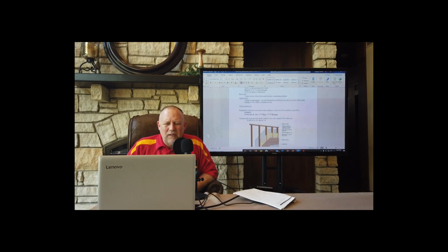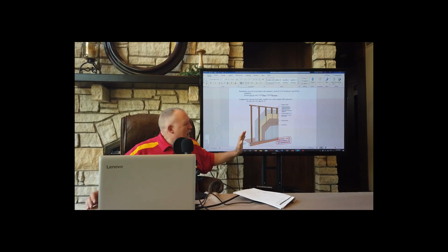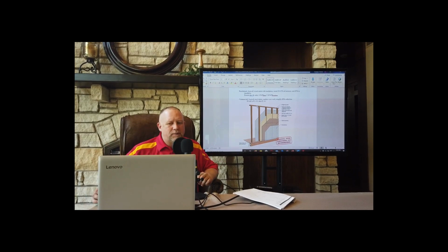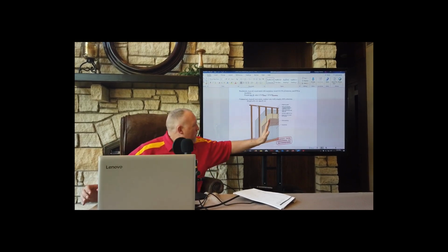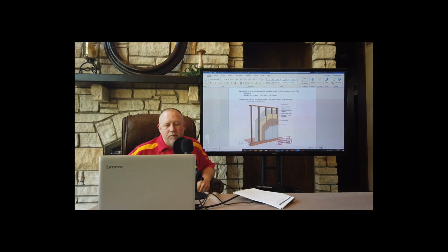Notice this. Go to page 14. So what a wood wall does is basically it's like two different walls, where one path through here goes through the sheathing, the insulation, and the drywall, and another path through here goes through the sheathing, the wood, and the drywall.